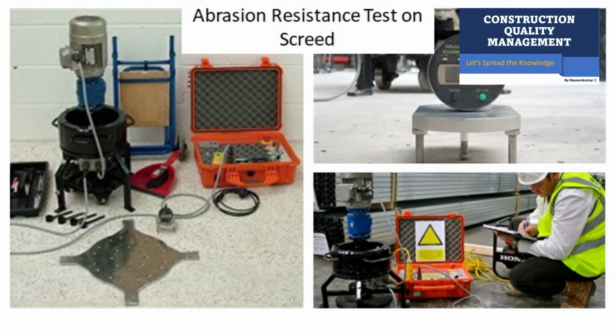In order to carry out this test, the testing machine is placed and fixed on a test body or a test area which has been marked by the client. After this, the abrasion head is allowed to rotate for a duration, as I mentioned, 2850 plus or minus 10 rpm for approximately 15 minutes.